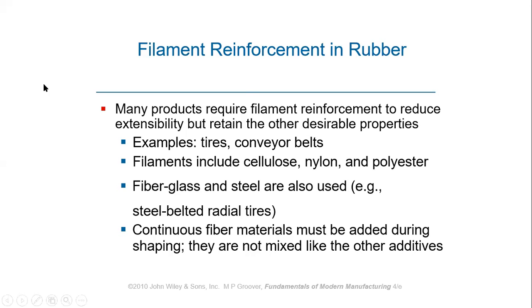Okay, and how to reinforce the rubbers using filaments. Most rubber products use them, like in the tires. If you cut a tire, you will see that there are some fibers available in the tire, or in conveyor belts, or any other belts. There are fibers inside the rubber actually, and that is the manufacturing of fiber reinforced composite. It's kind of similar to that. Those fibers are added. There are various processes. I'll show a few of them.